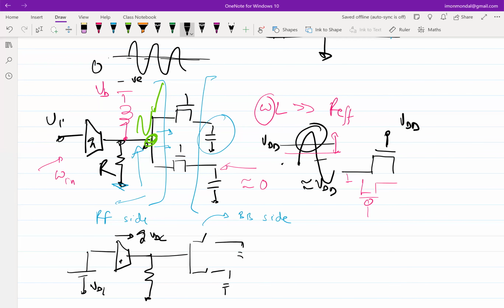They're absolutely identical, right? But there is one key difference. In general, the PMOS beta or mu p is lower than the mu n of the NMOS, which used to be the case even till a few years back. But right now, there are symmetric devices which are being made because of advances in devices.